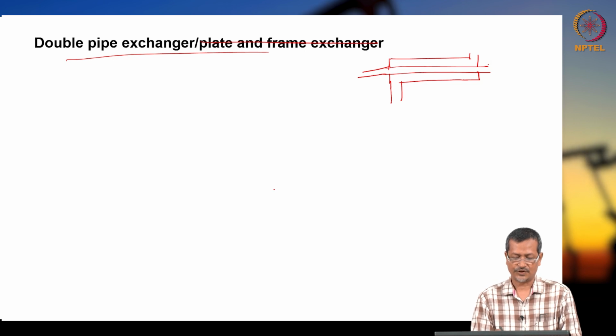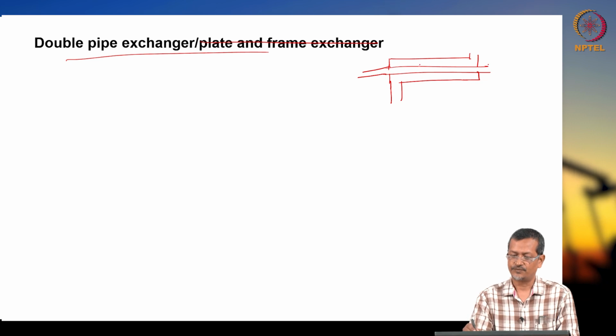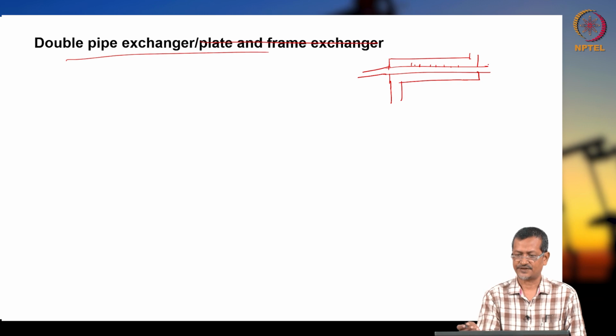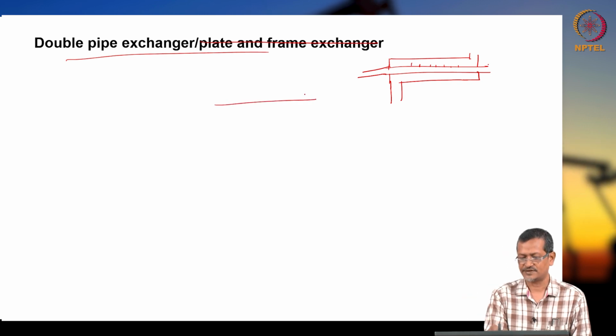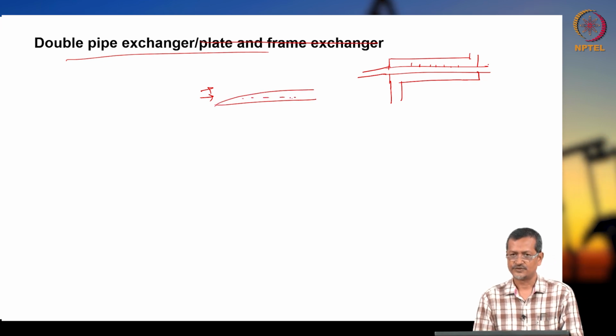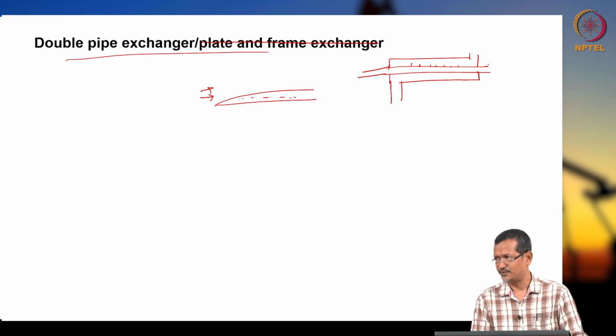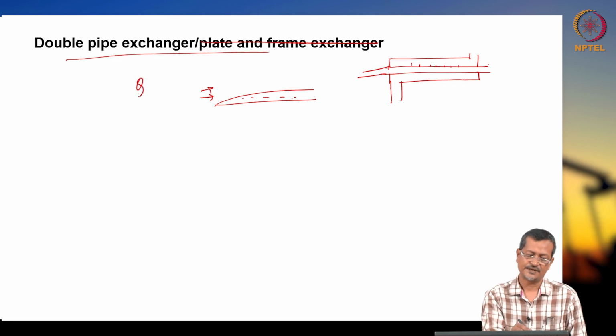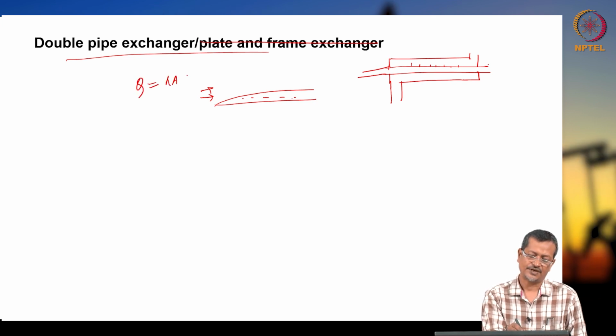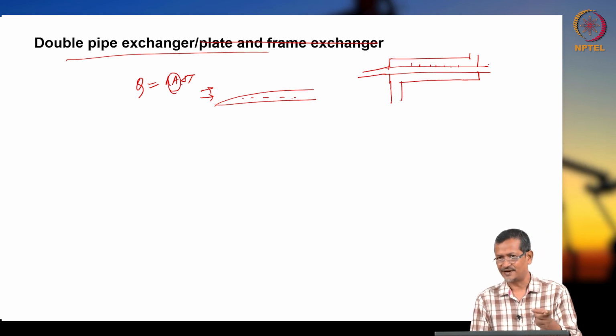So tube is often finned to give extra surface area. So tube will be finned sometimes. What is the purpose of fin? Fin means extended surface. Like I have one surface and fluid is flowing over it. So what will happen? One laminar layer will be created near the wall. When a laminar layer is created, heat transfer rate will be lower. So you create more turbulence, you create more surface area, because you can remember the formula H A delta T. If you can increase the area A, your heat transfer rate will increase.